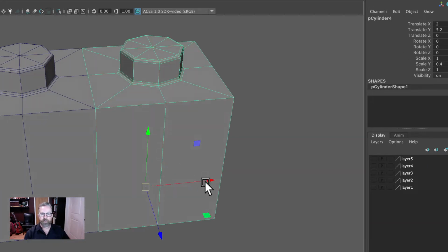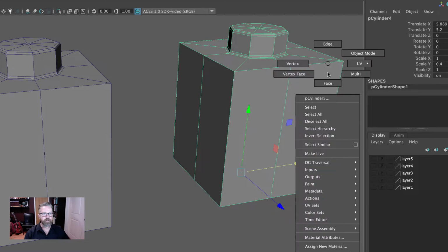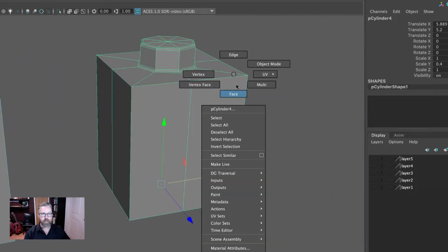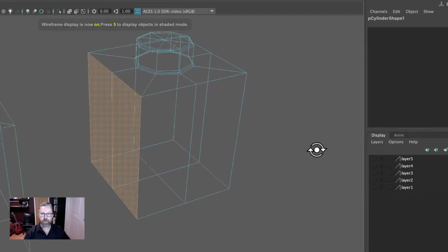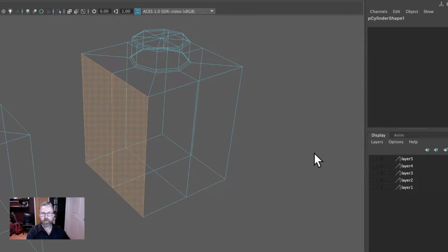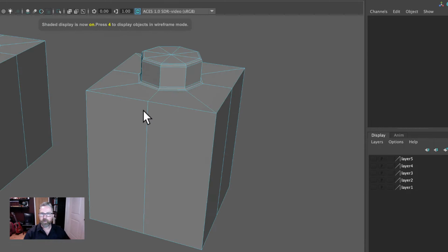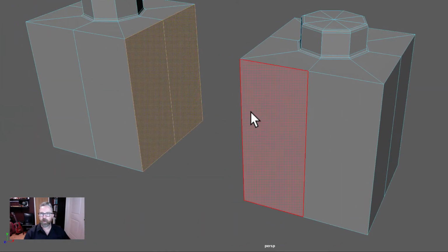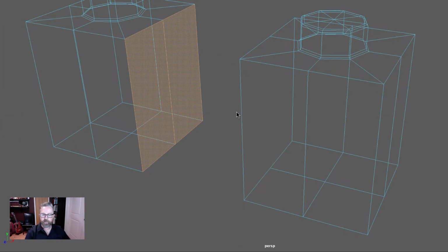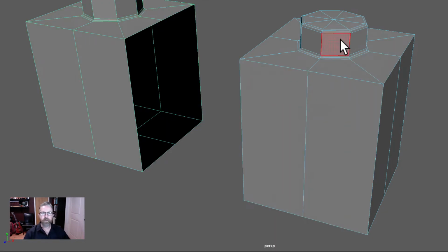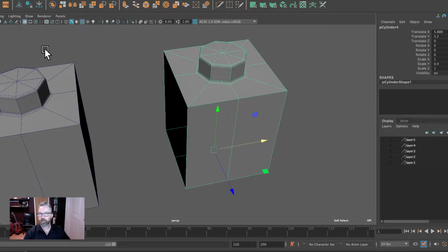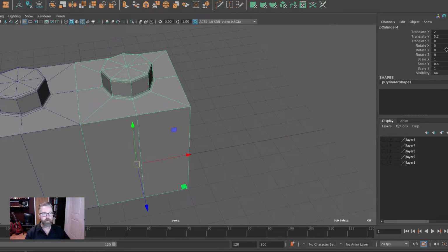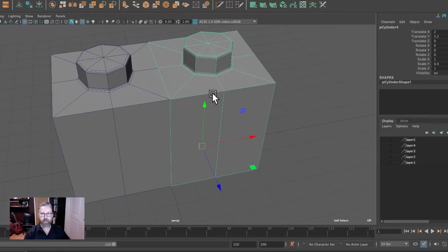Now you'll recall that we have to delete the facing faces. So we'll come and right click, choose face. We'll select the 2 faces, probably better with the Q key. Hit the 4 key to make sure we don't have anything selected on the other side, and we'll hit delete. And then we'll right click and do the same on this set of faces, 4 key, just to make sure. We'll hit delete, and now we can put this one back. We can grid snap back. Turn my grid back on so that I can grid snap. And we're back to 2 units on the X.